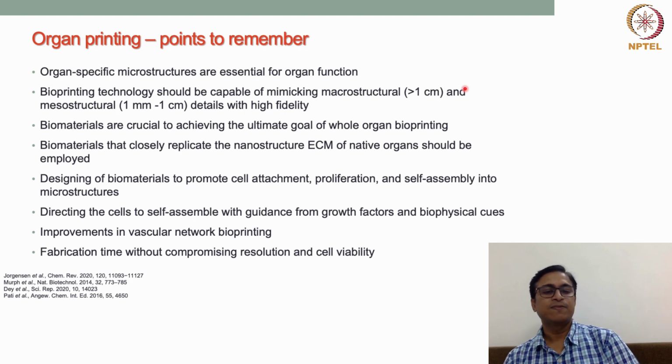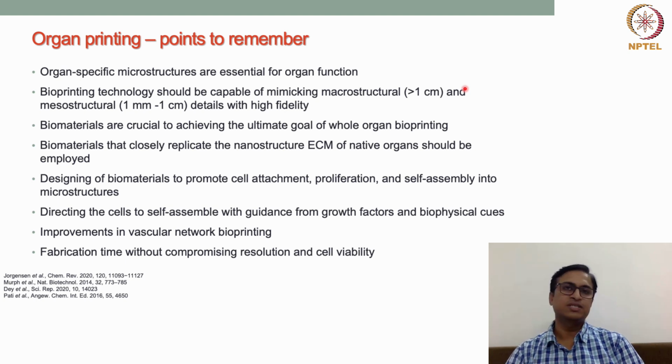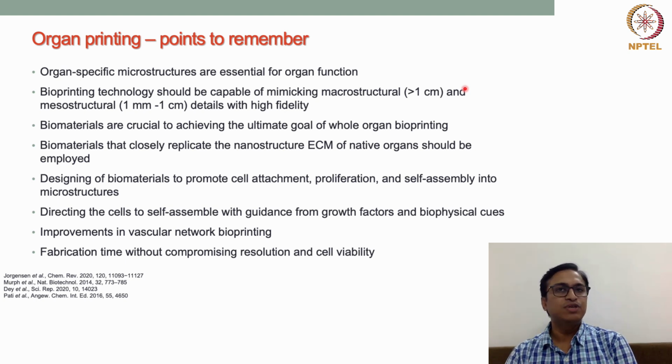Another thing is that we also need to improve the fabrication time without compromising the resolution and cell viability. We have seen earlier, while dealing with bioinks, that to improve the fabrication time we need very high print fidelity materials, and probably we need to work on the rheological properties of the bioink.